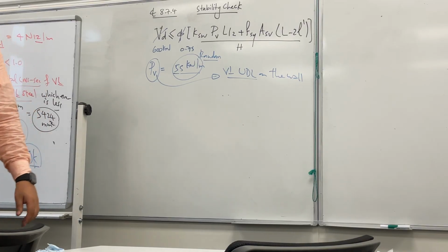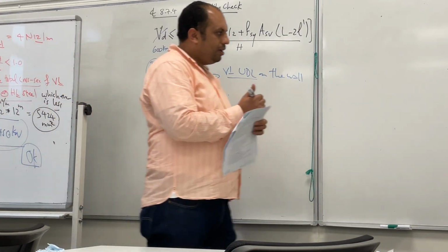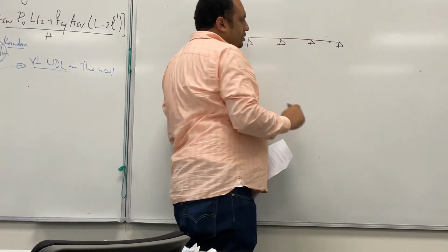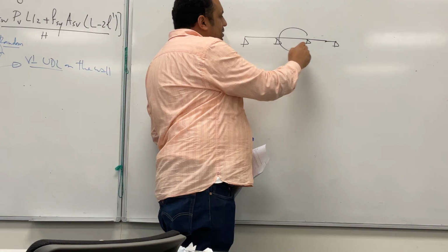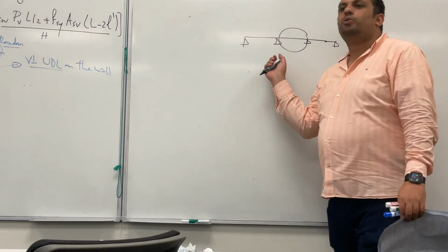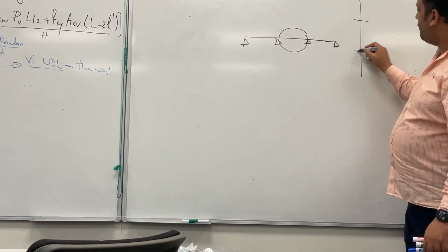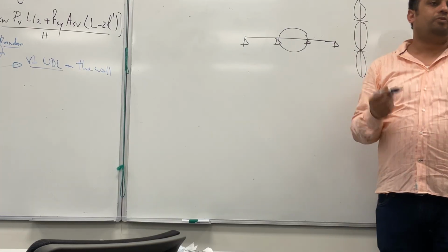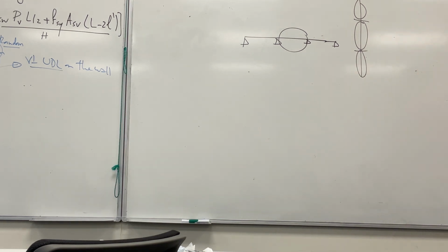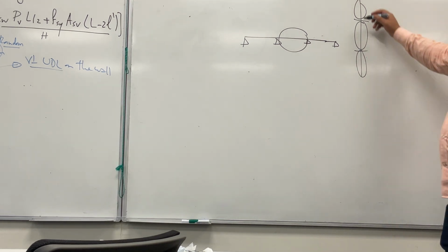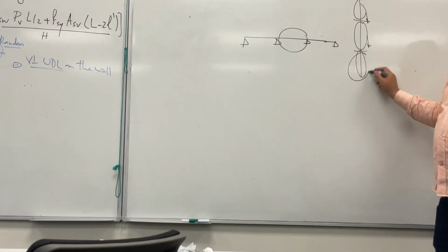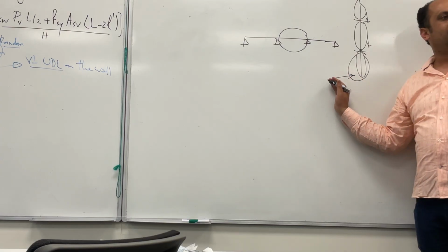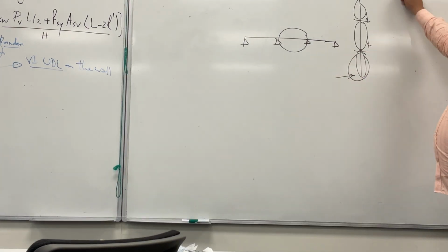Okay, guys. If you have a simple beam, the span is only between the supports, right? Here as well, if you have a wall, we have some supports. So this is not one wall. We have segments of the wall, like three segments. For the vertical load, because the load accumulates, which one is more critical? The bottom one. Because the shear also accumulates, which one is more critical? The bottom one. Only on the out of plane bending is it different.